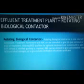Where a nitrified effluent is required, RBC can be used to give combined treatment of BOD and ammonia nitrogen, or to give separate nitrification of secondary effluent.